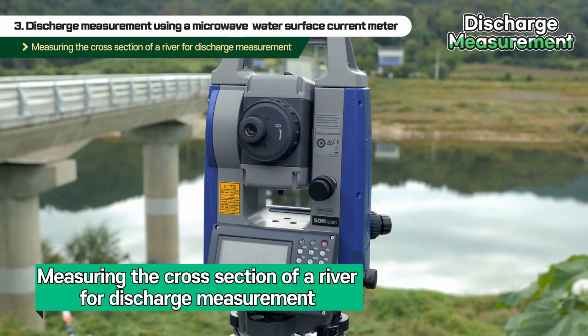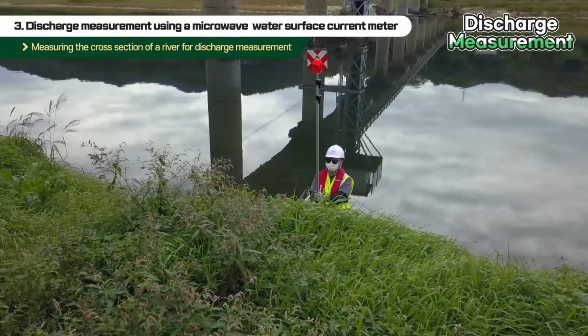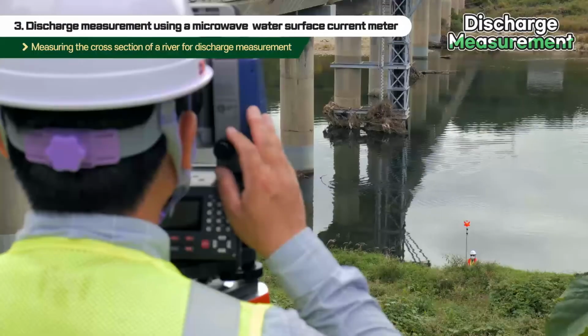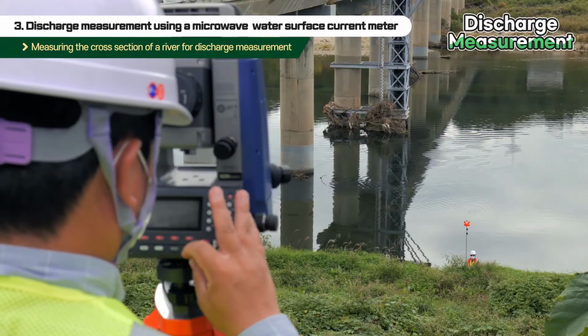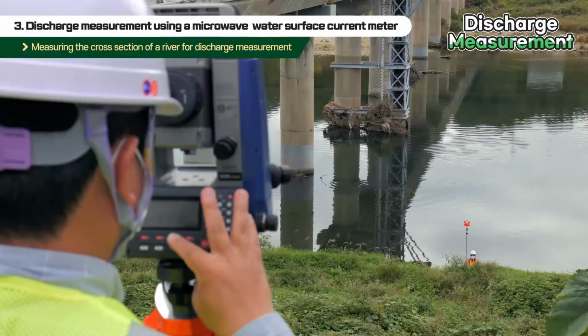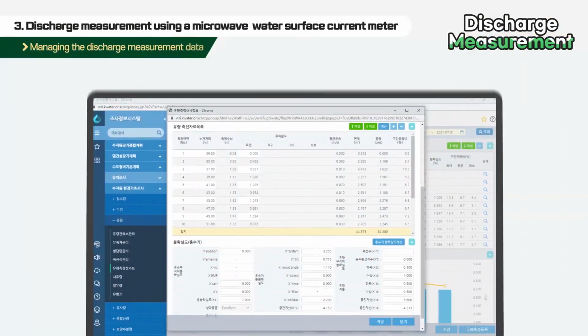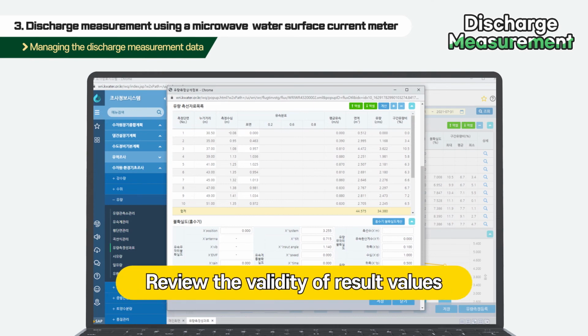You should measure the measuring points to calculate the discharge by using the measured current speed. The cross-sectional measurement should be completed before measuring the current speed, using equipment that can survey the terrain, such as a light wave rangefinder. When the current speed measurement is completed, discharge is calculated based on ISO standards through a program or system. The operator must review the validity of the result values from the calculated discharge.